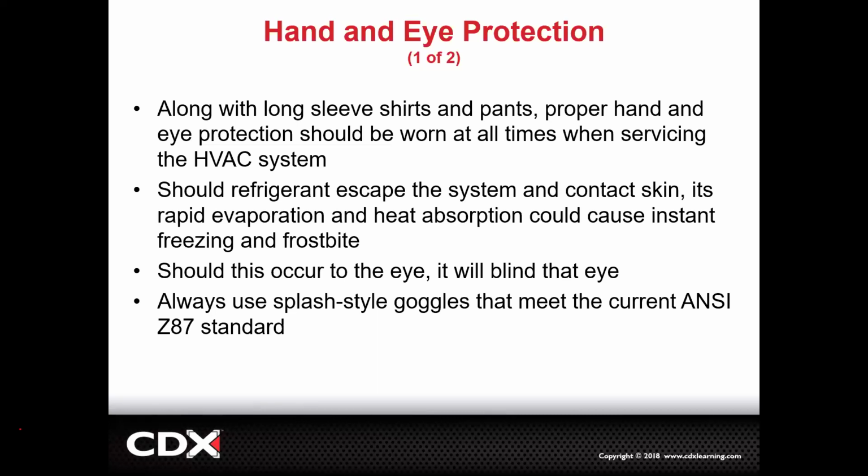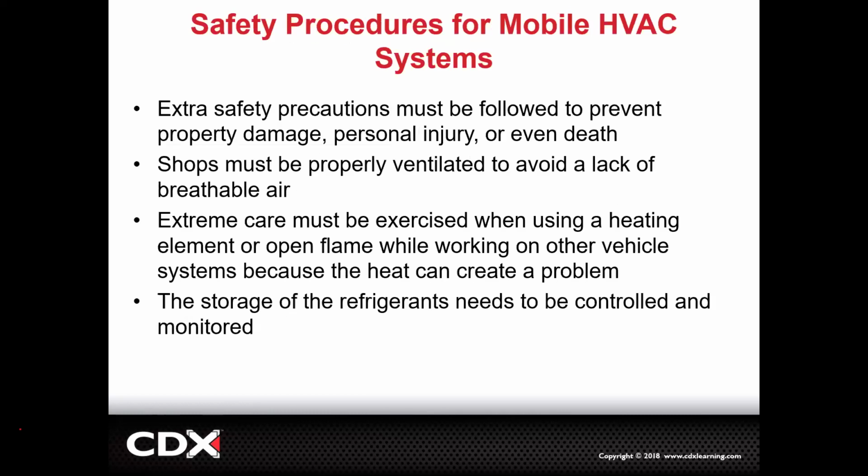There's a safe way to handle it. So we're going to, of course, do what we're supposed to do and handle it safely. But the PPE is still a good idea because once in a while, a hose is almost torn through and you move it just wrong, and all of a sudden, psh, you're getting sprayed. And of course, in your eyes would be really bad. If you were to get a direct refrigerant discharge into your eye, it will blind that eye. So we're going to be making sure everybody's using the correct PPE.